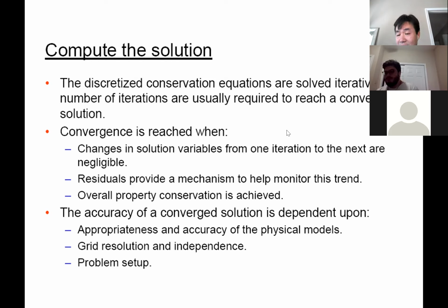Okay, for the unsteady run, basically you need to specify the time intervals. For example, I want to start the run from 8 o'clock. The next time I want to know is 8:01, 1 minute after 8, then 8:02. So I can simulate an hour from 8 to 9, but the time interval will be 1 minute, for example. So every minute, Fluent will calculate a set of results for you.